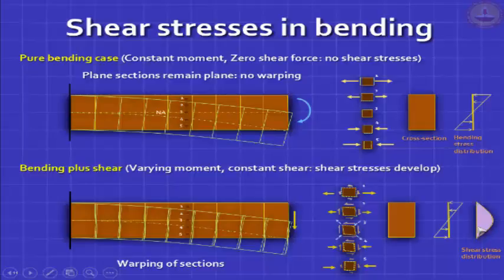The shear stress is 0 at the top and bottom because exactly at the top and bottom, you have a free surface. Remember, shear comes from friction between the layers, the horizontal shear. There's nothing to rub against at the top and bottom. So the shear stress has to be 0 there. We leave shear in peace there. We don't distort our understanding by including shear.